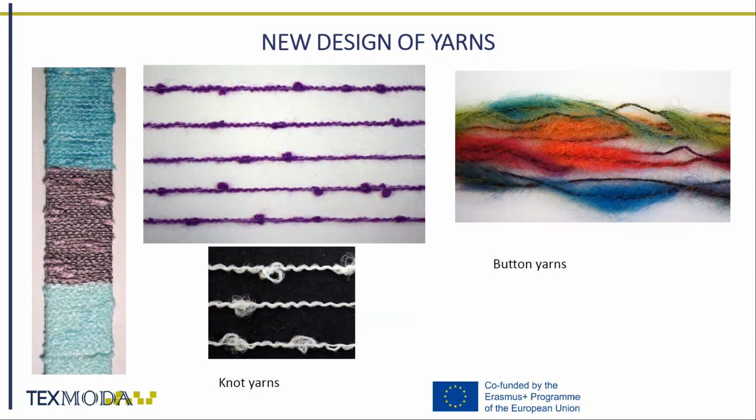Knot fancy yarns are with small or big, mostly twisted effects of one or a row of components arranged at regular or irregular intervals. When the effect component, usually roving or sliver, is covered up by the core component, button fancy yarn is obtained.